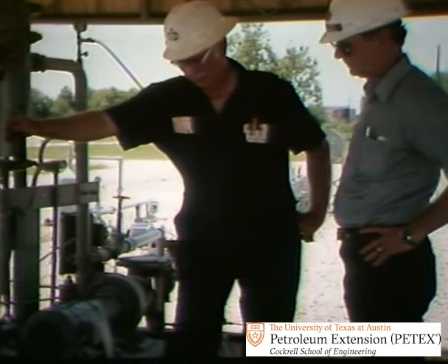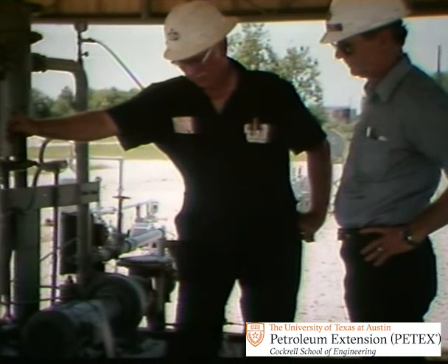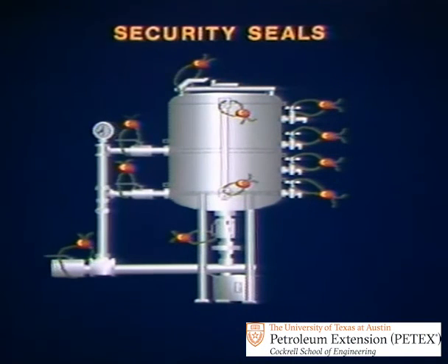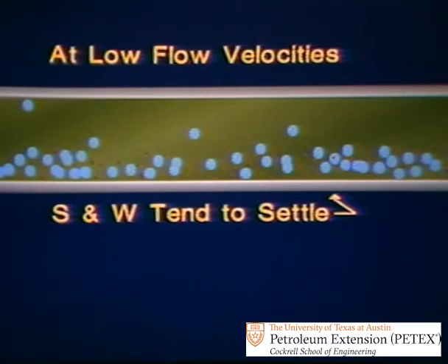In addition to good sample mixing, good sampling procedures are a must. Let's go over a few. To begin with, make sure all security seals are intact and that the sample has not been tampered with. Make sure the flow velocity of the stream is adequate. A stream flowing at less than the recommended minimum velocity will require some type of mixing device upstream of the sampling location, such as tees, elbows, or power or static mixers.